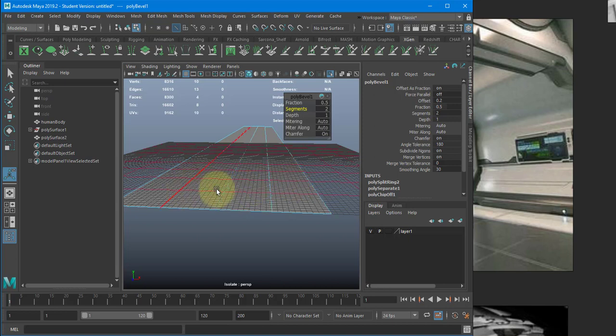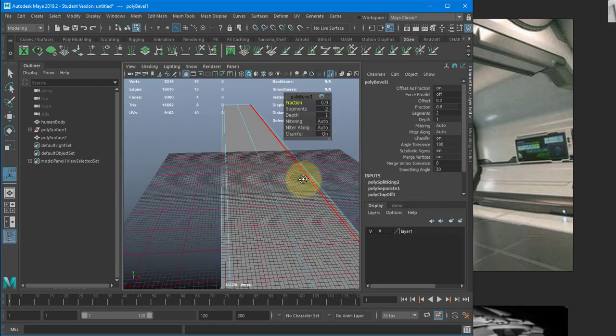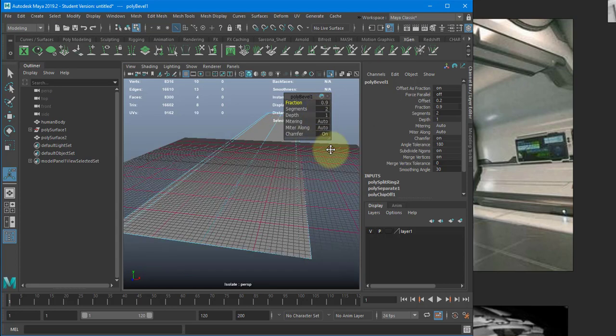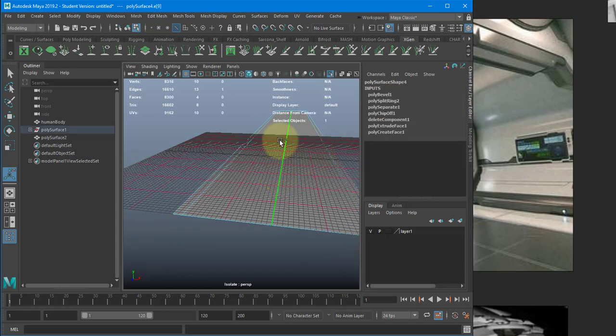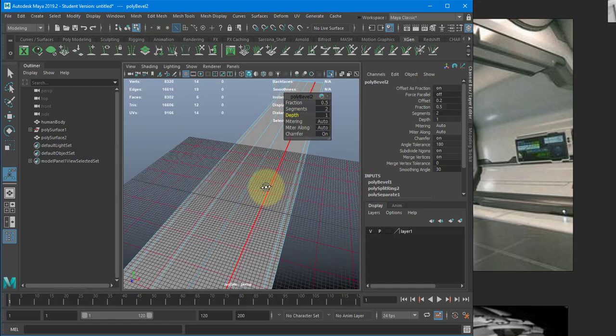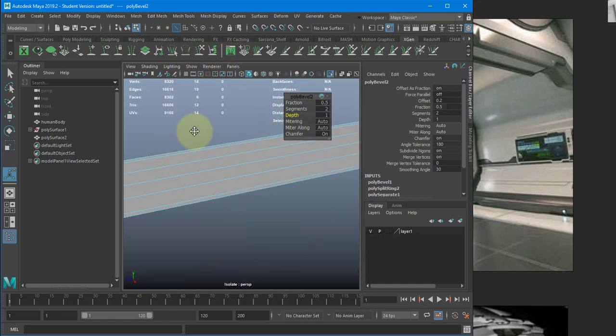So I'll have this here, this here. I'm gonna go a little bit further, like 0.7, I think. 0.9, yeah, that'll be good. Actually, I like 0.9 better. I'm gonna go with maybe a little bit bigger tiles here. Let me add another bevel here just to split the difference there. And let me hide the grid in this view. I don't need to see that.